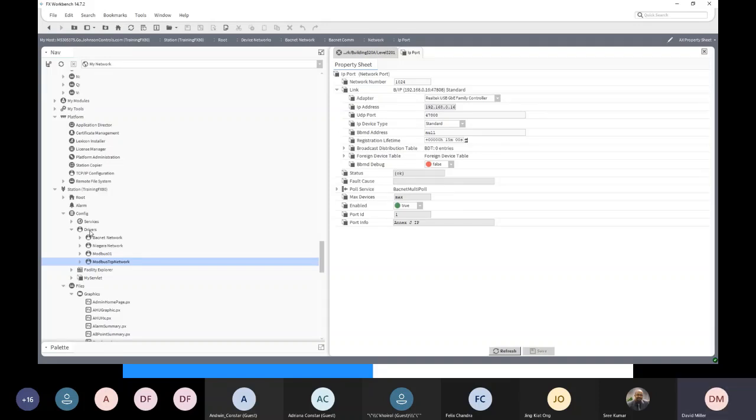So you're now looking at 1,000 points, not just one device. So you've got to have at least a 10 device license. What, 10 devices gives you what, 500? So you need more than 10 to get your 1,000 points out of a single Daikin BACnet device.